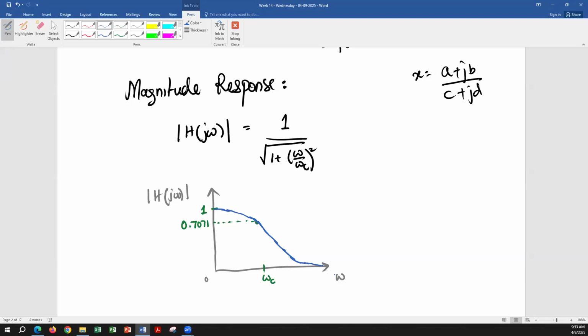So what's going to happen? If you don't divide the x-axis into equal distances, it's just going to push all that frequency where everything is happening towards 0, because the range is just too large compared to the initial part where your response is non-zero. You will just see it spike up and then go down, and you will not be able to see a clear response of the filter. I'm going to show you in MATLAB so you know what I'm talking about.